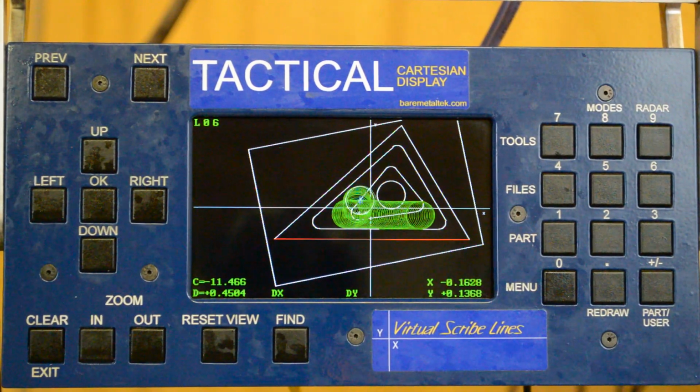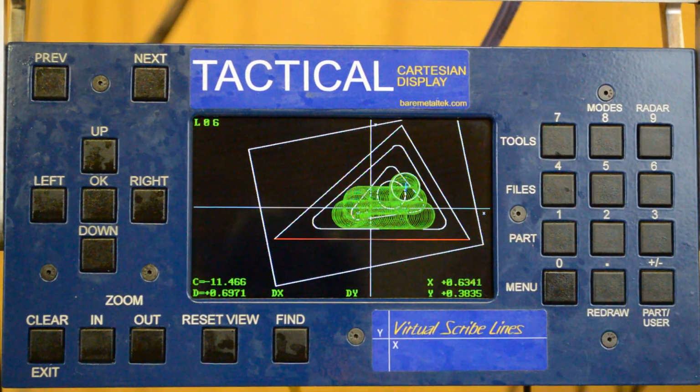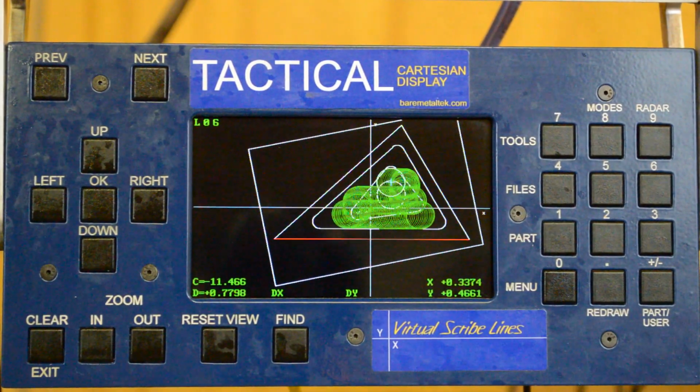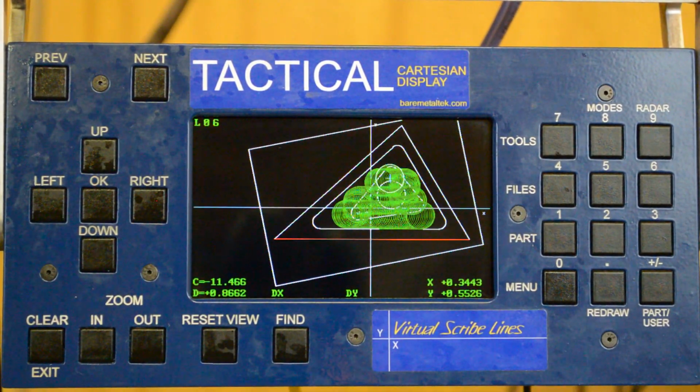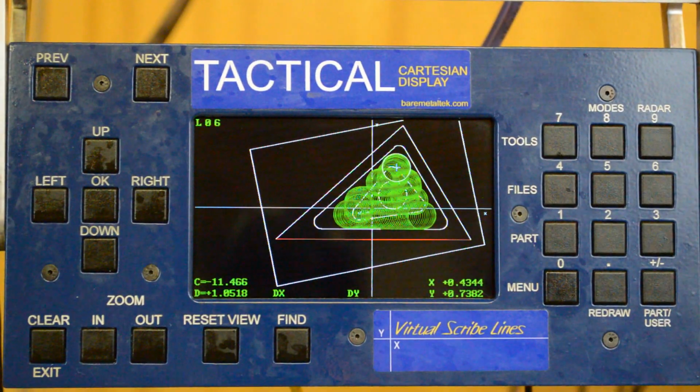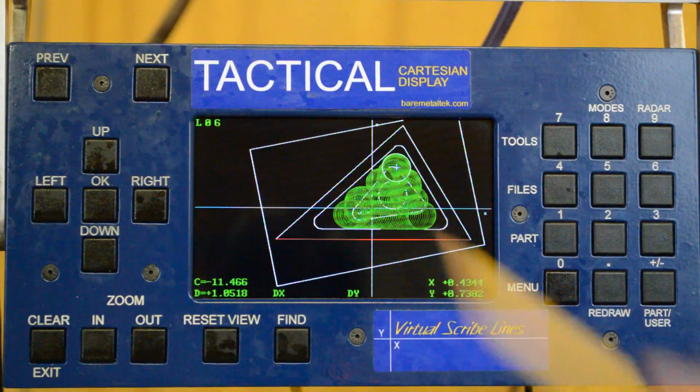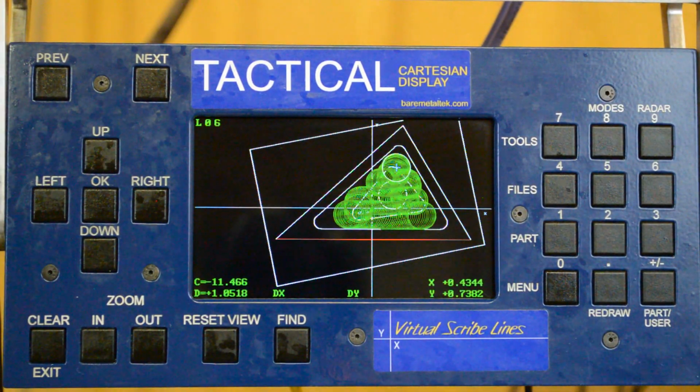There's not a lot of room to navigate inside here, so I'm just going to hog all that metal out of there the best I can with this tool. Then we're going to go in with progressively smaller tools to get into these corners and stuff. So I'm just going to take advantage of that 1/2" end mill while I've got it.